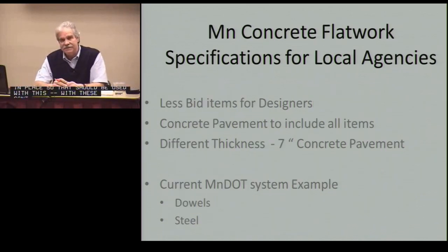On the designing side, the idea was to have less bid items for the designers to include and not to do a complete joint layout. If a joint layout is done by designers, that's fine. Otherwise, the specifications say, the flatwork specifications, if there is no joint layout, the contractor would provide a joint layout that would be reviewed by the engineer. So the idea is to make it simpler.